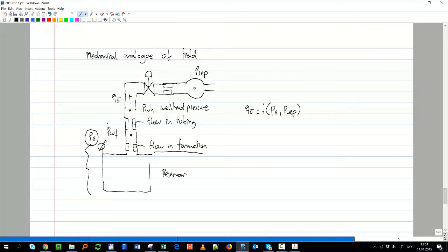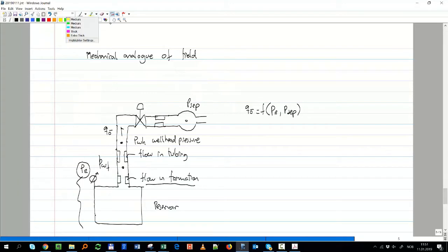So what can I do to keep the rate constant? What would be the solution of a control engineer? The control engineer looks at what he can control. He says, well, this valve here. I can put here a flow rate meter to measure rate, and I put some input to a control system, and that goes to that valve. I actuate that valve such that I keep the rate constant.